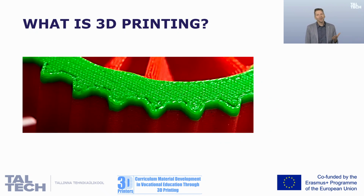Okay, here on this slide you can see just one example of what the surface will look like after printing, when we make this close-up picture of the surface. Depending on the layer thickness, there are layers visible. If we have thicker layers, it probably takes less time to produce, but the layers are visible. If we use thinner layers, it has a smoother surface and is more accurate, but it generally takes more time.